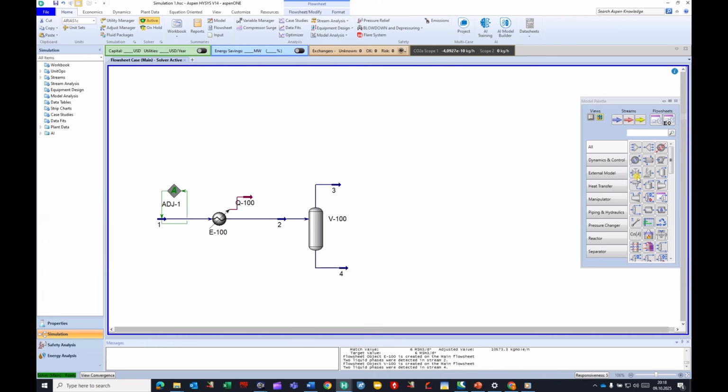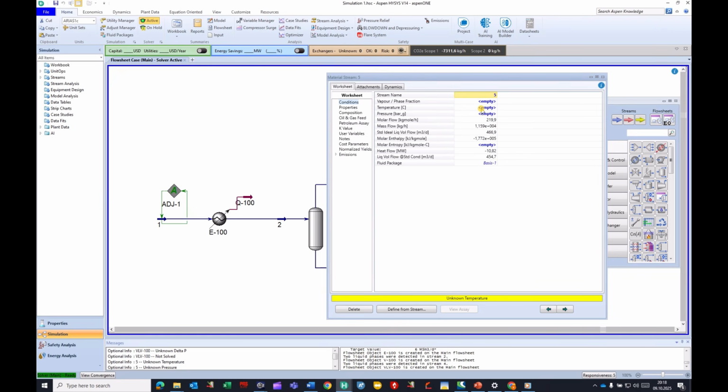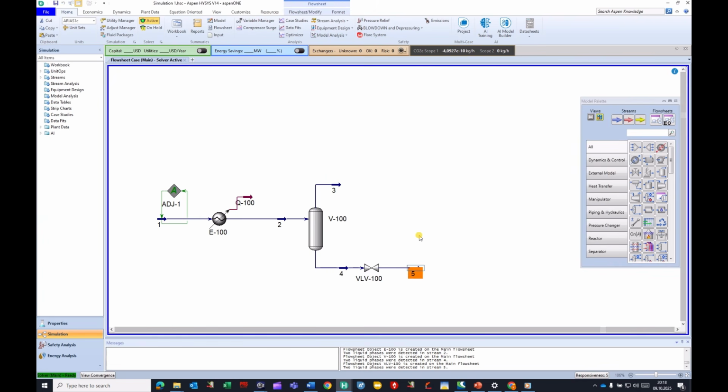For the liquid one, in this case, we have a lower pressure downstream, so only a liquid control valve is enough. The pressure based on the schematic was 12 bar gauge. So I'll put the pressure, and for the valve, at this stage, that is enough. Later for valve sizing, I will make another session. For heat exchanger sizing, for the cooler sizing, I will also make a session, and the rest. So this session is only about the overall simple simulation of the compression loop.